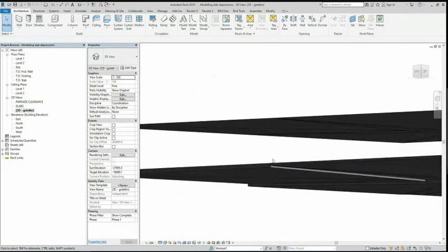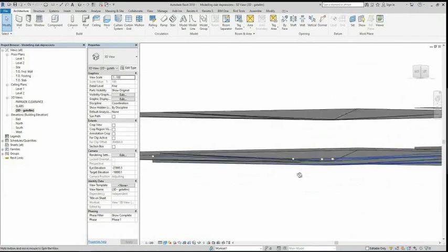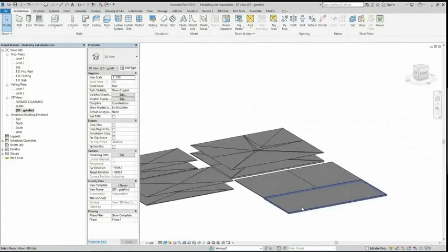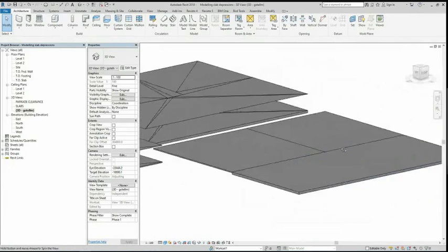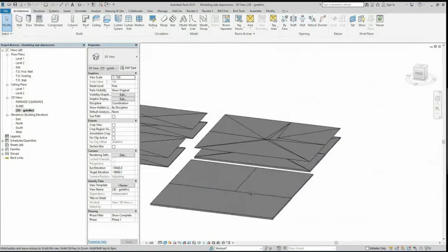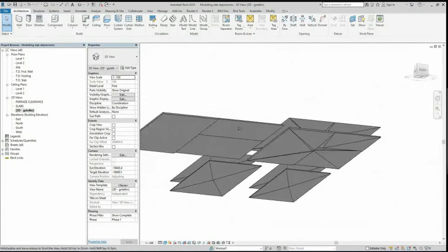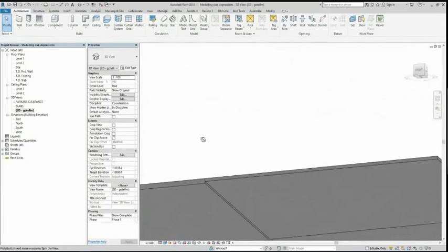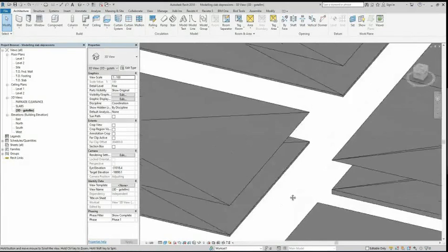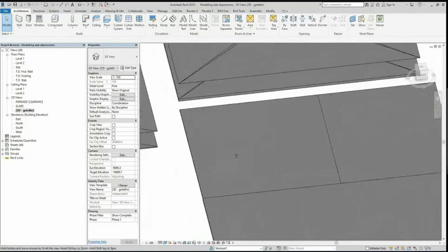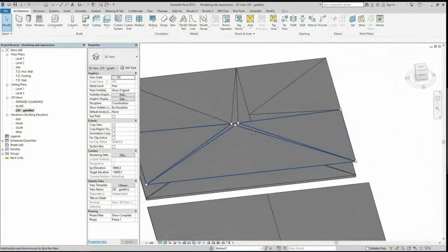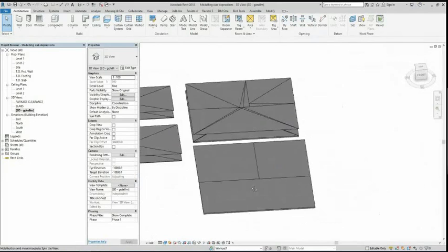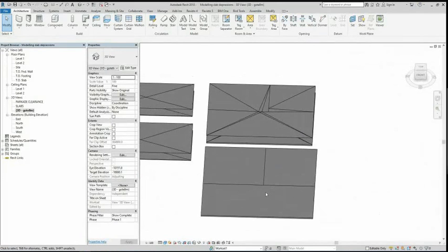I'm going to change the visibility here so it's a little bit easier to see. So you can see here that you have varying thicknesses of slabs, which you'll probably encounter in parquets quite a bit, or other structures as well. So I thought it would be helpful for you to know how to create a depression where you have these multiple thicknesses. The next step is to create a sacrificial, I like to call it a sacrificial floor element,